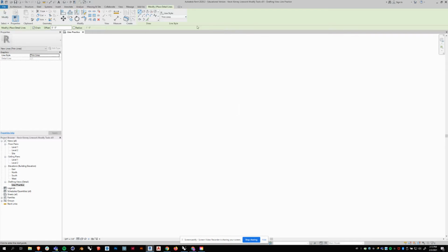All right, so here I am in my tools, and let's just click on the line tool. I'm going to click once to start the line, and click another point to end the line. As you can see, that little dimension string sort of moves with it. I'll do a 3-foot line. Now I clicked again, then I hit escape to end, not the tool, but at least that line. Now I can start again. 8 inches, click, hit escape, ends the line, but I'm still in the tool. Click again and kind of move.